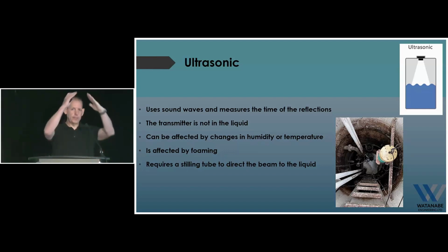These tend to have a very wide beam angle on them, so it will pick up things on the outside edge. And if you get grease buildup, it will definitely pick up on the grease buildup. So you might have to do what they call echo profiling to make sure it's not picking up stuff that it shouldn't. And the last thing there is to sometimes stop it looking around the outside or picking up things on the outside of the wet well.